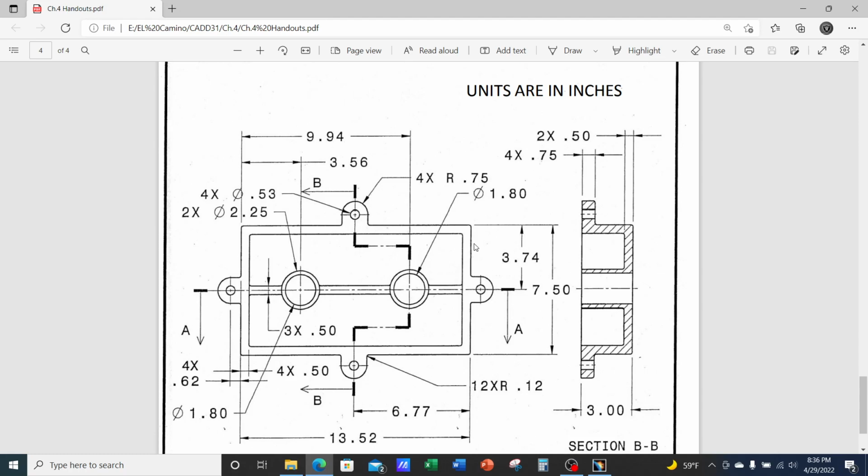So if we want, we can actually sketch on this surface, or we can sketch at the bottom and pad up to this surface, or vice versa. I'm going to make, once again, the sketch at the base of the shafts. And it doesn't appear to be symmetrical. So I'm going to have to use these dimensions.